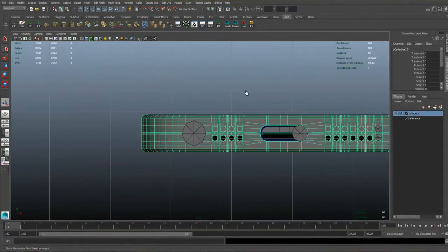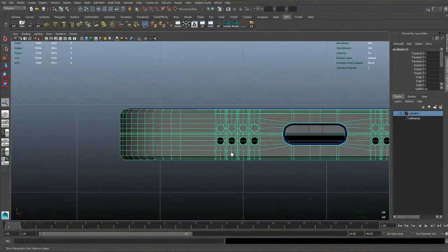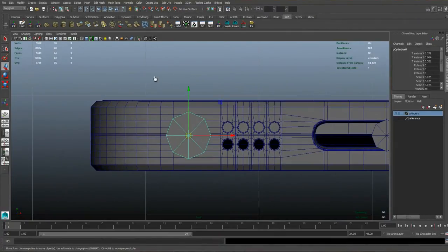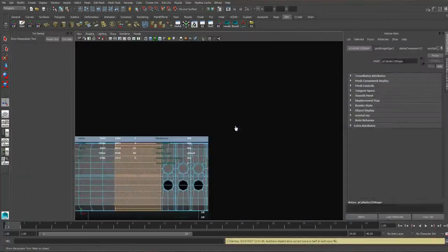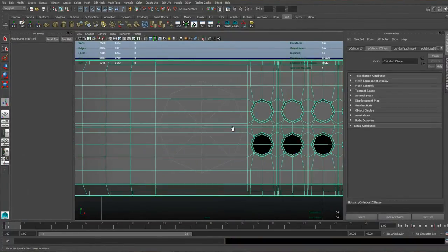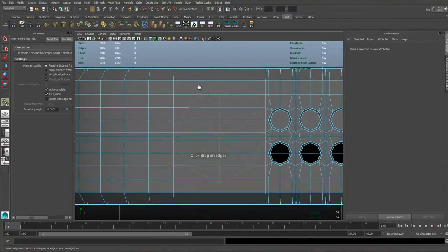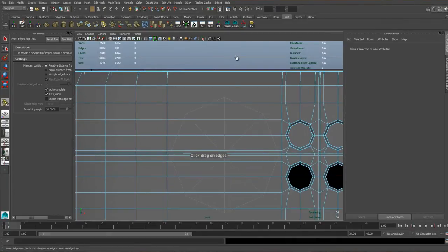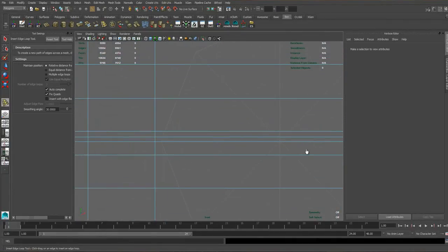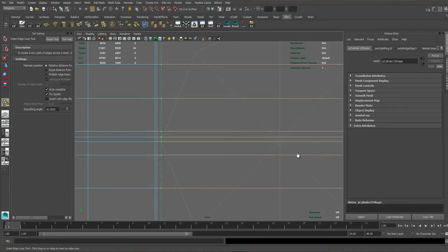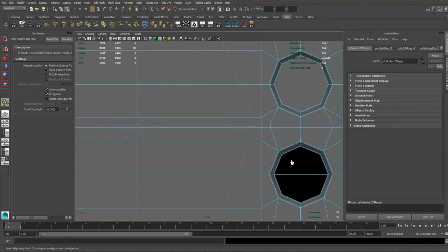And again, because this cylinder is on the corner there, and I really can't be bothered to work out the corners today, I'm just going to move this to this empty space here. And now we're ready to do the headphone jack hole. Now it's important that these edges do not ever meet the edge of the headphone jack itself. So I'm going to move some stuff out of the way before we get started. I'm going to need an edge loop. I need 2 edge loops around this headphone jack, and there's not much room to work with.